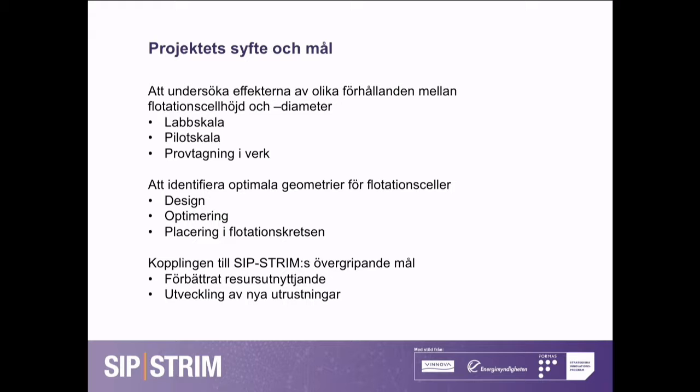So the way of the bubbles and particles up to the surface, to the foam on top, is increasing. You have changes in the hydrostatic pressure. You have changes in the distribution of the pulp. And all that is of course affecting separation and separation efficiency within the flotation process.